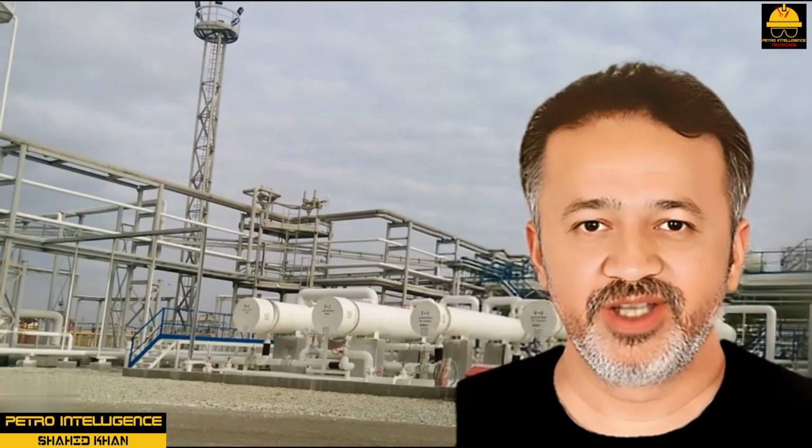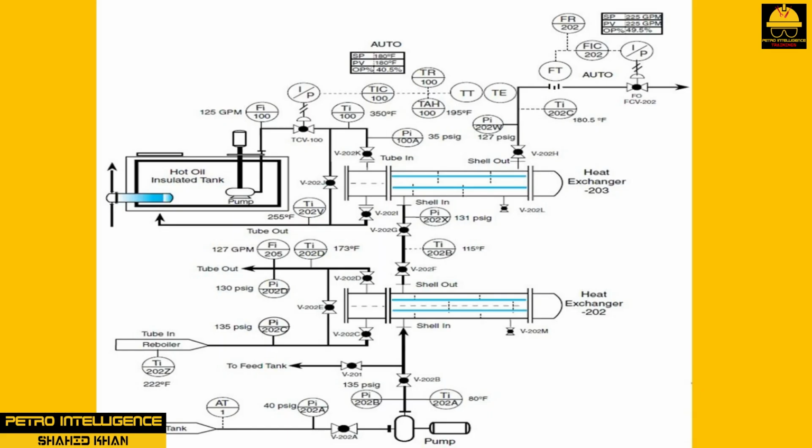Startup procedure for heat exchanger system. Prior to startup, the feed tank has been blended, sampled, and prepared for introduction into the heat transfer system for processing. 1. Notify your supervisor and all concerned about startup: downstream process technicians, I&E, engineering, maintenance, etc.